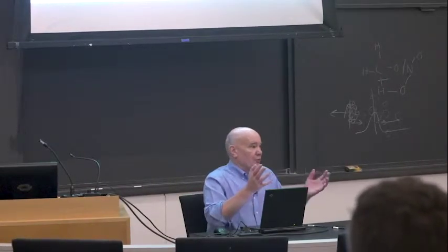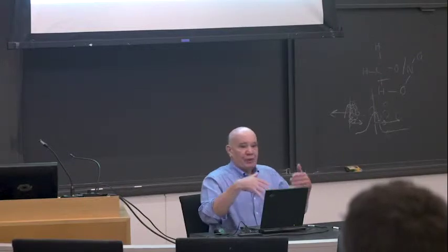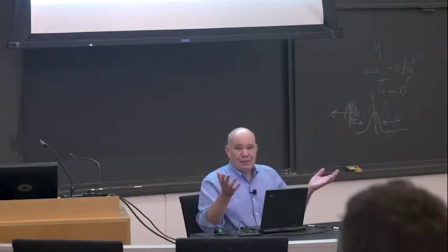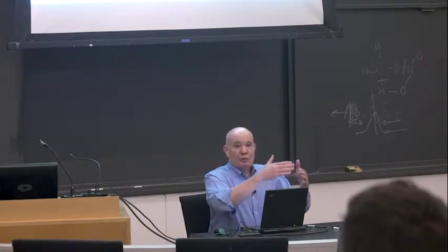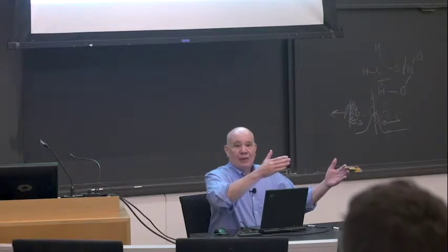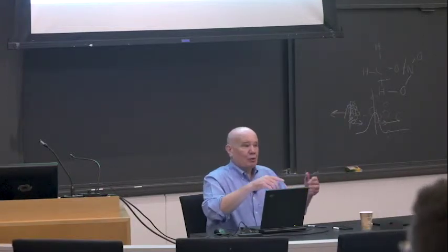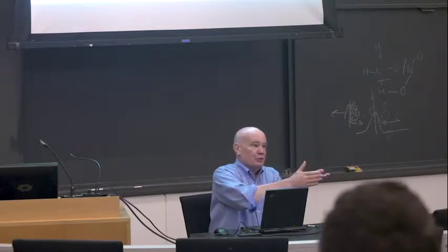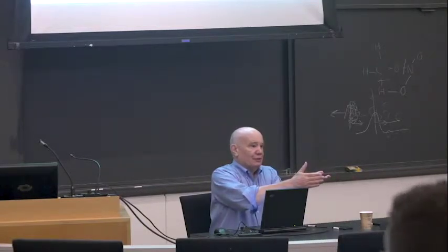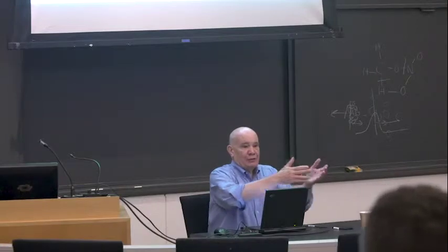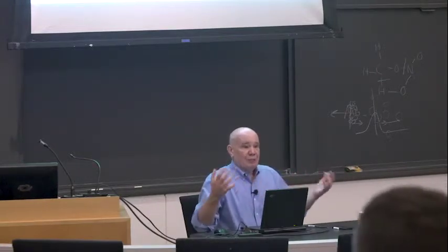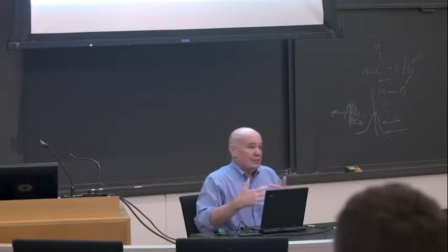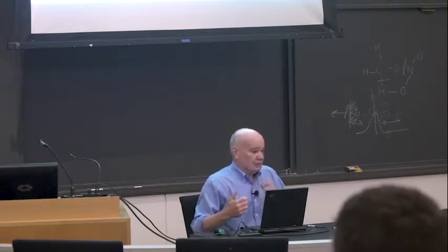But if I have something like a carbon particle that has a very high vaporization temperature, it's not going to have vaporous carbon going outward. I'm not going to have this envelope flame. What I'm going to have now is the oxygen in the ambient coming very close to the surface, and I'm going to have a surface reaction. And whether I have a surface reaction or a vapor phase reaction changes the combustion dynamics, okay? And it changes the ease with which I can get the final products.